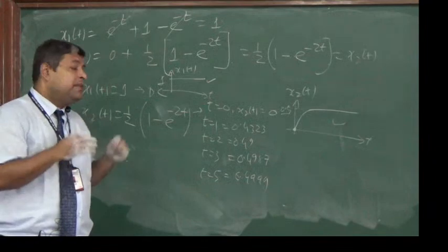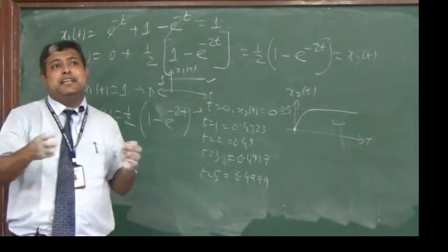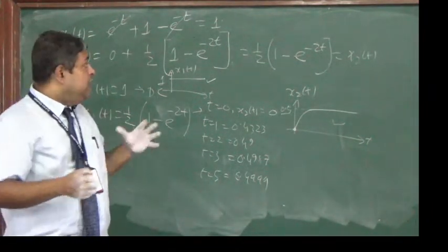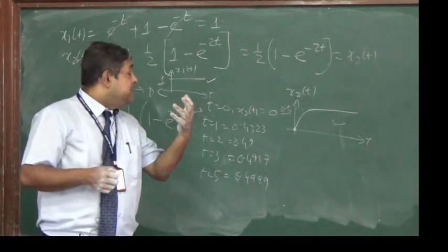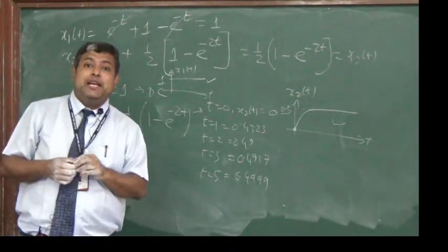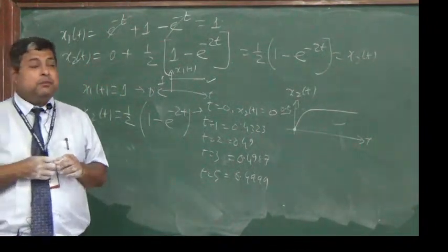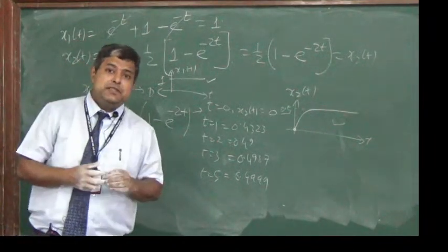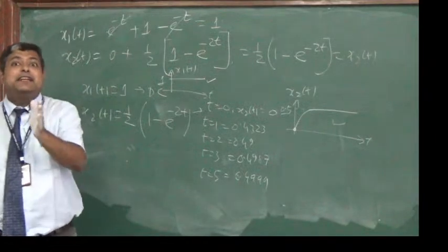First aspect: if the total system is an interconnection of many systems connected in cascade, then for that kind of system, if you are using transfer function based modeling, we cannot get the intermediate intricate details. But for the state variable model, we can get the internal details of the system much more easily, because we are tracking the states at every time instant.